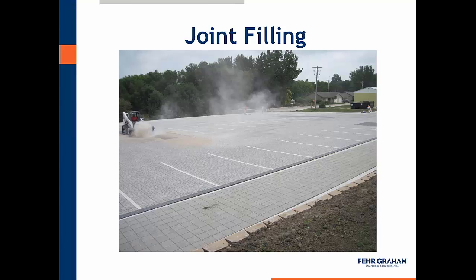And by filling up those joints with the chips, we are able to keep out dirt, sediment, dust, whatever particles will land on a parking area. It just helps keep that a little cleaner and more open. Not that there isn't future maintenance with vacuuming and cleaning, but it really helps out in keeping that overall system operating like it's designed to.